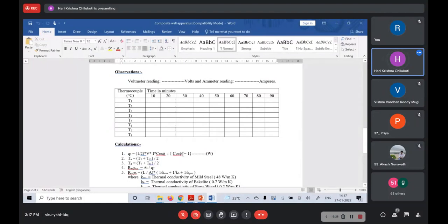And as you know, the thermal resistance is equal to the driving potential divided by the heat transfer rate. This is the common definition for thermal resistance. A similar thing can also be used for electrical resistance, or even for resistance to mass transfer. In all the cases, at the numerator you have the driving potential. For heat transfer, temperature difference is the driving potential. And at the bottom, you have the transfer rate. In this particular case we are dealing with heat transfer, so at the bottom we'll put the heat transfer rate, that is Q.